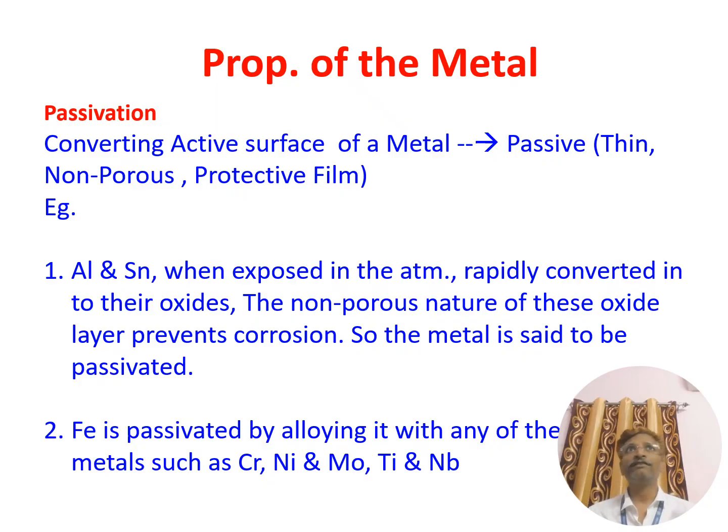Just imagine you have two metals, like silver and tin, both exposed to a chlorine gas environment. Silver reacts with chlorine to form silver chloride, and tin reacts with chlorine to form tin tetrachloride. So both form their respective chlorides, but silver is protected and tin is corroded.